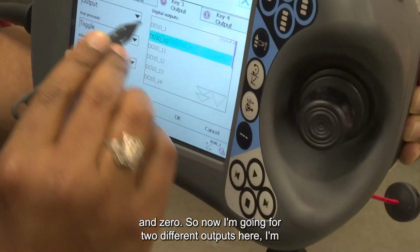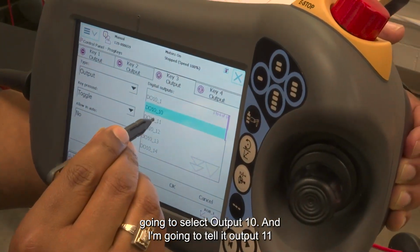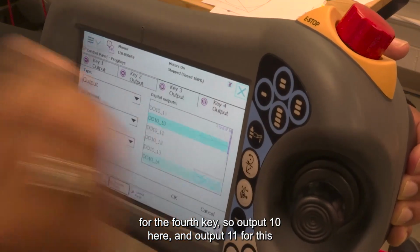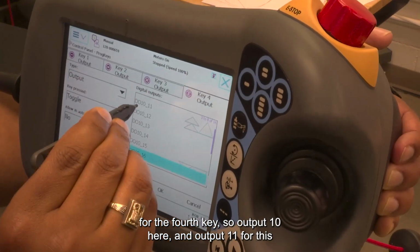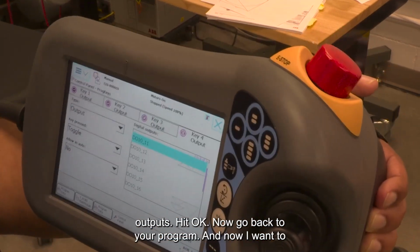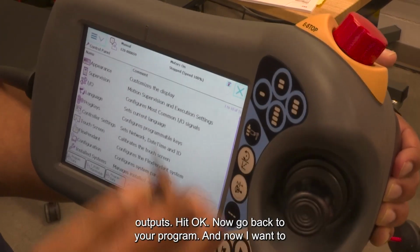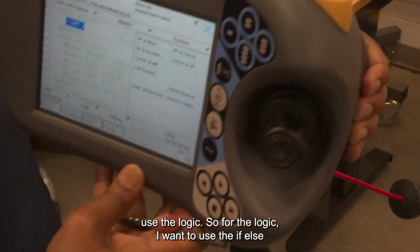So, now I am going for 2 different outputs here. I am going to select output 10 and output 11 for the 4th key. So, output 10 here and output 11 for this key. So, I have assigned these two keys to those digital outputs. Hit OK. Now, go back to your program, and now I want to use the logic.